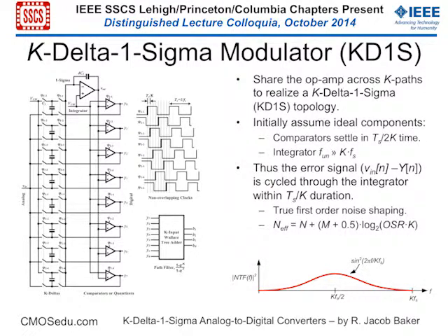This takes in this very simple idea: forward path isn't critical, reverse paths are. So I'm going to put the things that can be a little sloppy in the forward path, the summing of the signals. And then in that feedback path, I'll put my K deltas for trying to average what's coming in.